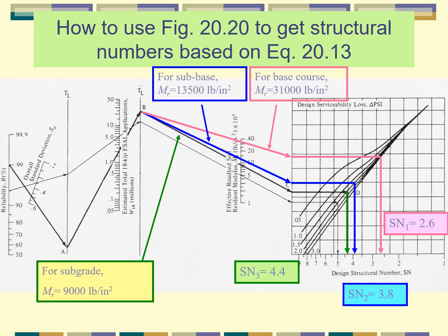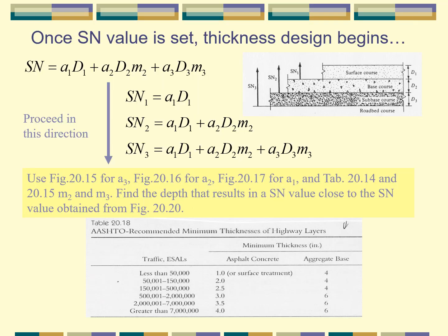And what about the subgrade? Above the subgrade, you are having the total pavement, entire pavement. That means subbase, base and surfacing. So you are getting this structural number, this one. So this is meant for the entire pavement. From this figure, you can get more clear perception.